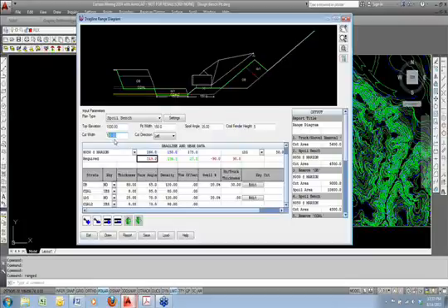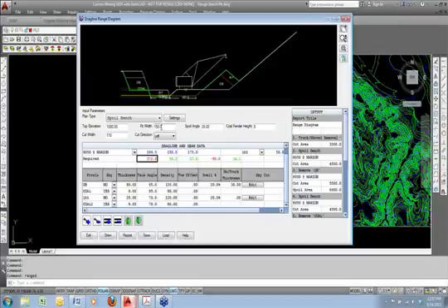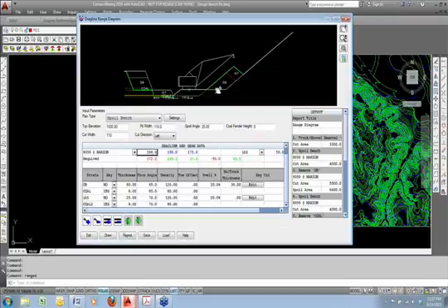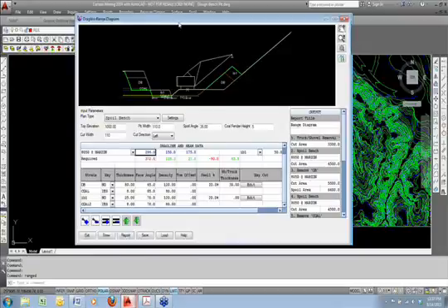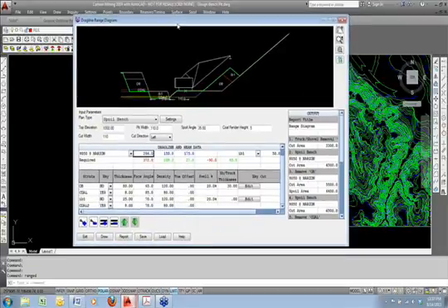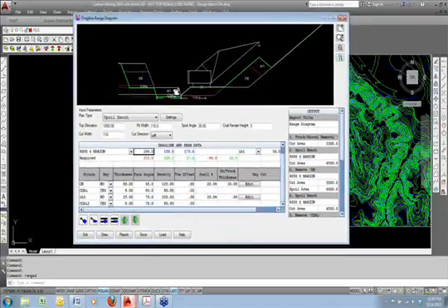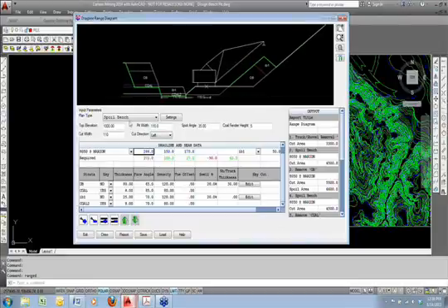So maybe if I drop this down to 110, and this to 110, I'm down to 372. My dragline reach is only 286, so I'm still not going to do it. So you just play with the numbers to size the reach or the range of your equipment. It's useful for finding your pit width or to find and size a dragline based on your digging methods.